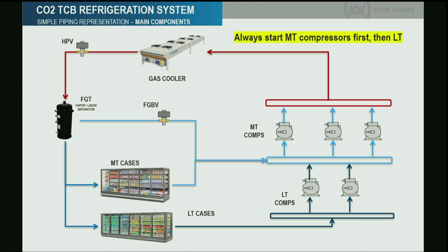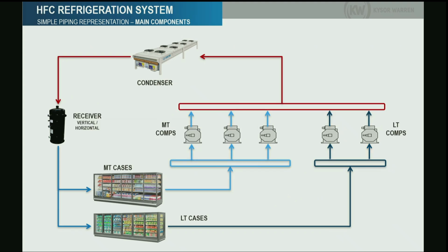In HFC systems, you don't have that concern, because whether you run the medium temp first or the low temp, they discharge into the same header, and then you can have your system running. So this is something to notice if you're doing a CO2 system startup.